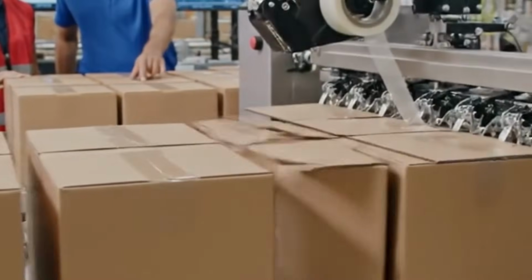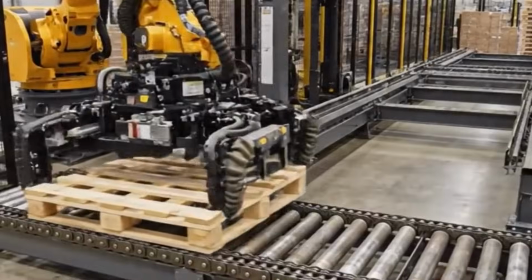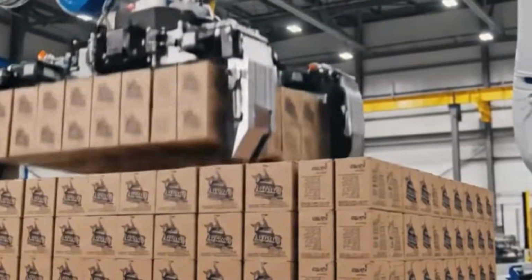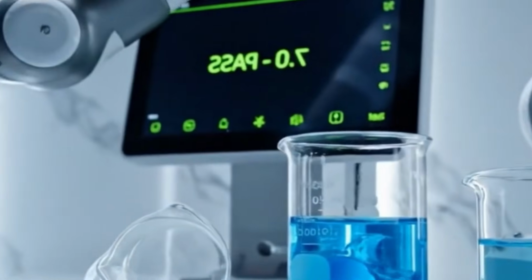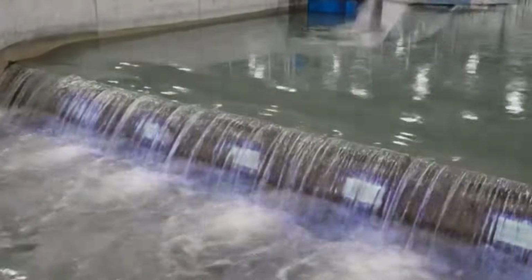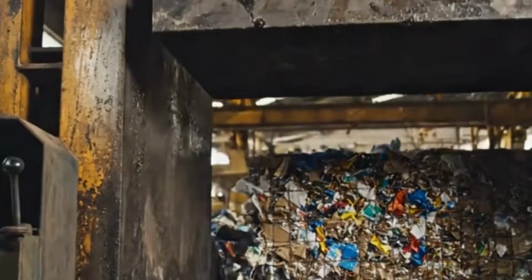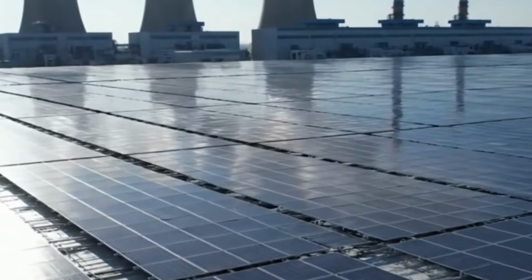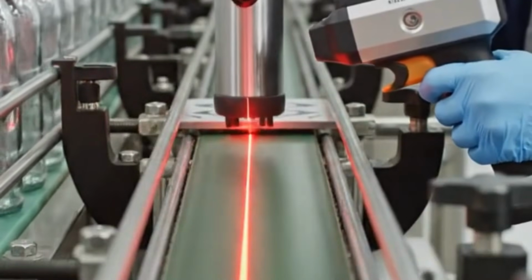Colorants are added in the form of water-soluble dye solutions or color dispersions. Each colorant is pre-weighed and diluted before dosing. Magnetic stirrers or inline static mixers ensure uniform dispersion. Optical sensors may be mounted over the mixing tank to confirm target Lab color values in real time. Preservatives such as methylparaben, propylparaben, or sodium benzoate are added next.